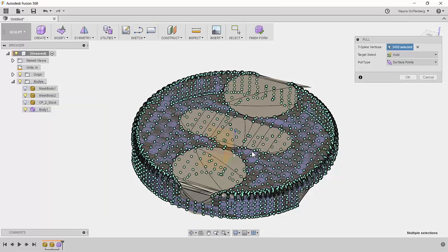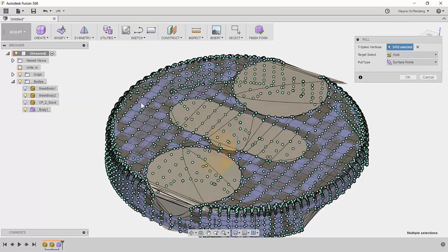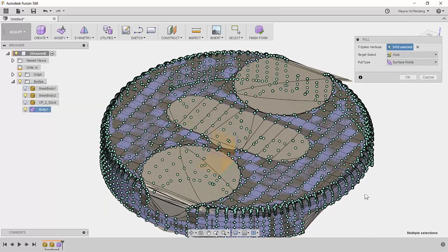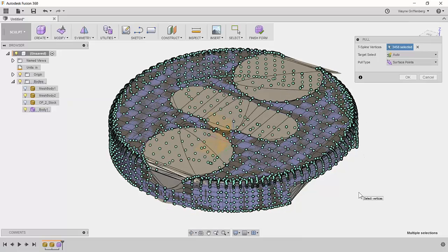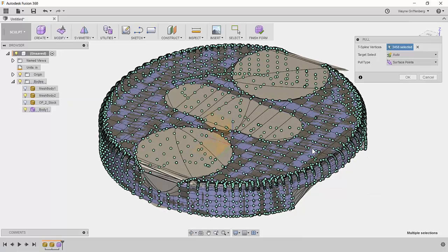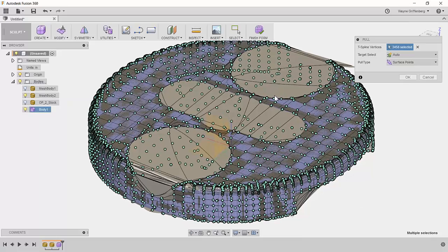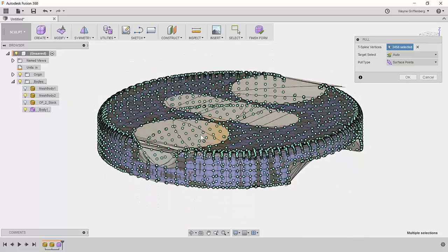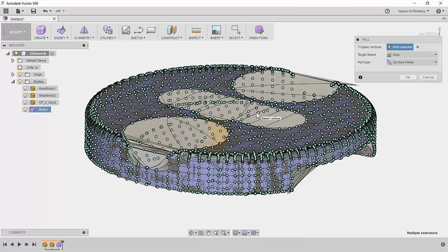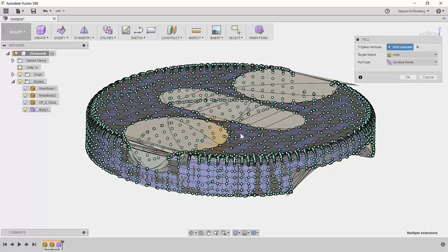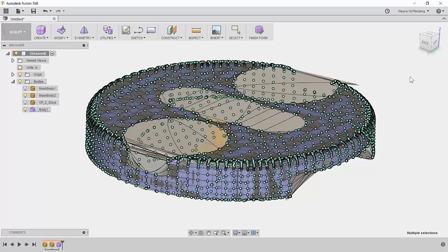So what we're doing is we're making that T-spline. We're trying to match up the facets, if you will, of the model. I only use 24, but of course you can get much more refined with your model here. But just to save a little bit of time and be able to show you, this is a quick way that you can pull those T-splines and the surfaces, if you will, onto your mesh body. I say OK, and now we have a body that represents the basic shape.